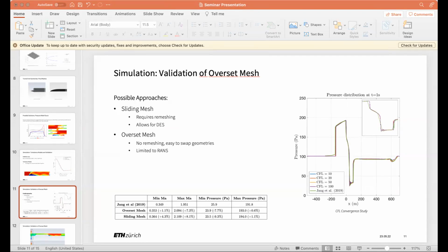but we're going to talk a little bit about the heat transfer in the final report, and we don't think it's as big of a factor on the tube itself because the heat transfer between really low pressure air and concrete is going to be really small, but it will be a design consideration for the leading edge of the pod. Great.